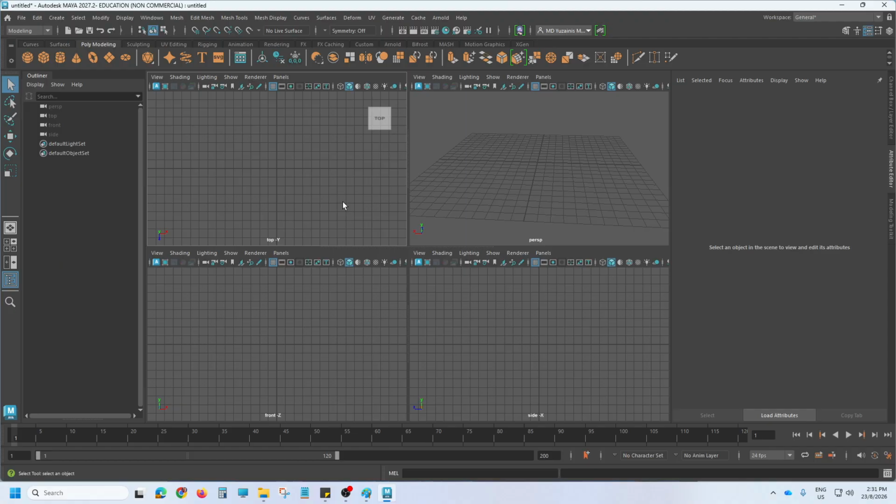If you click a view, you will see a thin white outline showing that this is your active view. If I click here, this will be my active view, and you will see it by the compass here. This view cube pops out based on which active view you selected. It's like a compass that shows you your orientation in the 3D view. For example, if I look here, I'm looking at the back part of the view, so I should work on the front, looking like this.